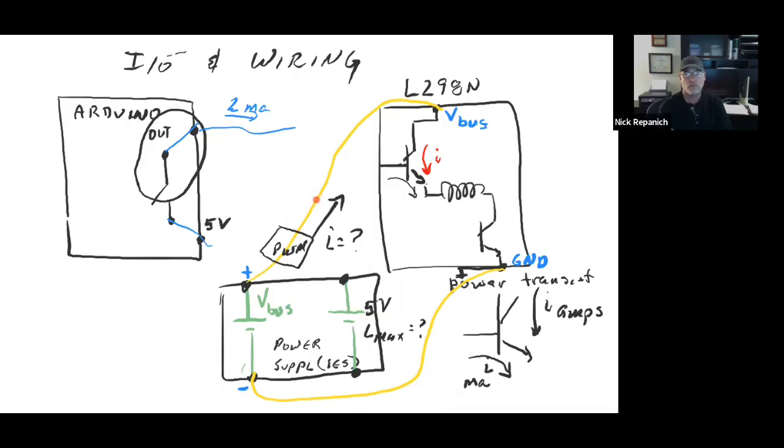So don't make them too complicated, but they sure help you to do it right. So that's what I'm looking for before you turn power on to anything. And after a while, when you do this, you're going to have high confidence that when you turn power on, it works because you went the right way through the transistors and you knew that the current limit was right. And every now and then you'll make a mistake and flip plus and minus, because we all do. I still flip plus and minus sometimes.